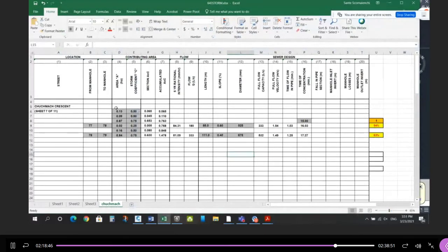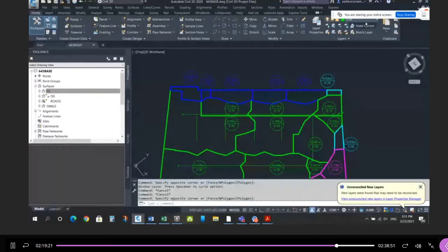So now I've just proven that if I add additional area to these two pipes, the flows increase, but they don't go beyond the capacity of the existing pipe. So there's no negative impact on those sewers. I can do this, and I've proven to the municipality that it's possible without any undue harm to the original pipes. And that's something you need to demonstrate, right? Just because you think it could happen, this proves that it can happen, right? And that's an exercise you would have to do if you're going to reroute any flow to a different originally intended location. So we can do this.